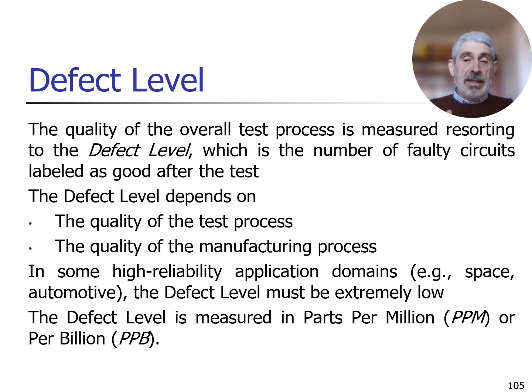Now, the value of the defect level depends basically on two factors. The first one is the test process. The better the test process, the lower the defect level. However, be careful because the defect level also depends on the quality of the manufacturing process. If the manufacturing process is nearly perfect, it produces very few faulty products, and even a medium quality test process may produce a relatively low defect level.